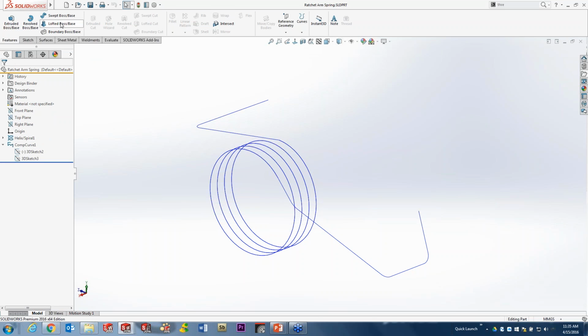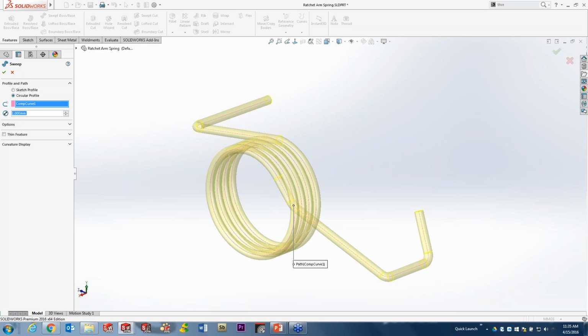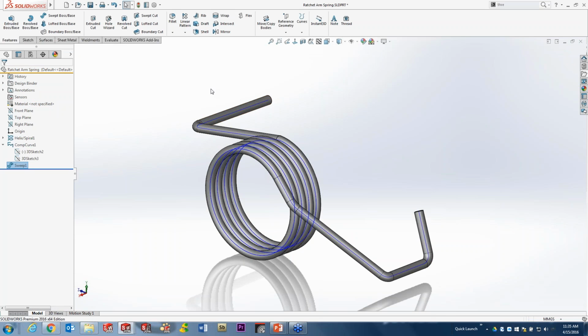Now what we're going to do here is make a basic sweep. But once again, I've not created a sweep circular profile, which is typically on a plane out there at the end and located properly. Here we just say instead of using a sweep profile, we're actually going to use it as a circular profile. Just make it a circle. You just tell it what the diameter is. All we need to input now is the curve we're using to drive it, and that is it. No longer have that extra entity located and pierced out at the end, and one more thing to potentially break if you do make a drastic edit.